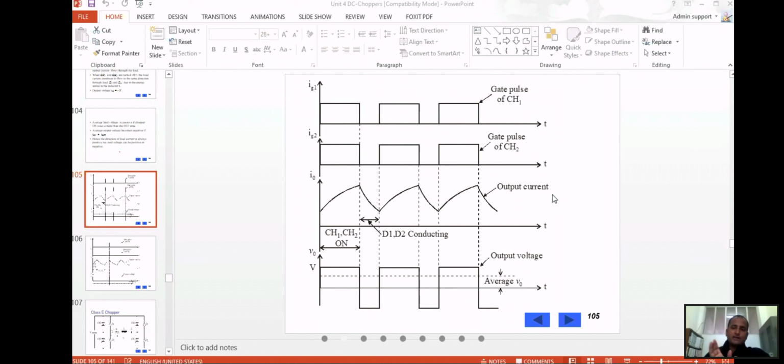So in frequency division multiplexing, we are dividing the frequency; in time division multiplexing, we are dividing the time. So, in terms of communication, each customer is allocated a particular time. But in the case of frequency division multiplexing, we are dividing the frequency, so each customer will be allocated a particular frequency.